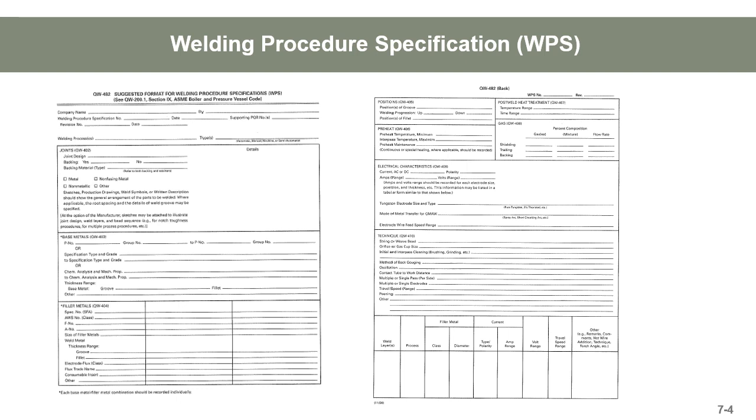One of the problems with welding procedures and PQRs also, that people that aren't really initiated into the craft have problems with, is that they'll end up thinking they have to fill in every blank on the WPS or PQR. You don't have to fill in every blank. You just need to look in the code and address certain variables, the essential and non-essential variables that need to be addressed depending on what you've got going on. On a WPS, you have to address essential and non-essential, and on a PQR, you just need to address the essential.